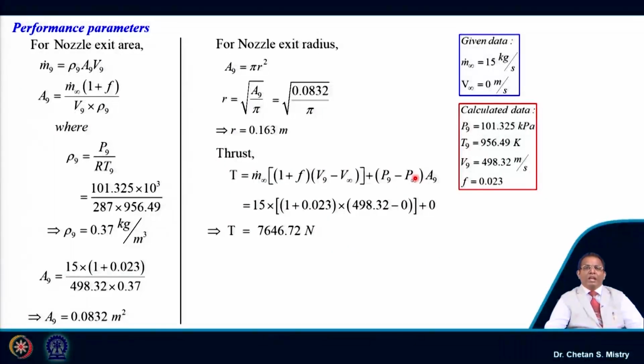Okay. So, you can imagine this number when we say our pressure ratio is 3, my turbine entry temperature is 1200. If you recall, in last lecture I was showing the information about the small engines and they were also having the thrust in this range. So, you can understand the purpose when I say UAV engine manufacturing company or UAV making company, they are planning for this engine design. So, this range needs to be carefully understood.